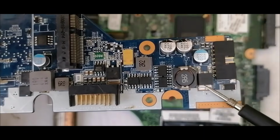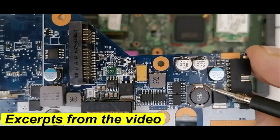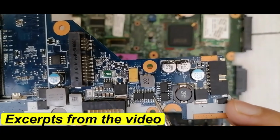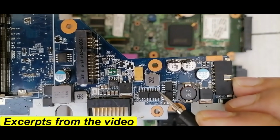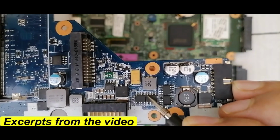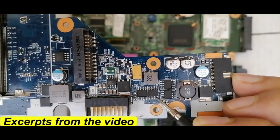So this is a 3 terminal MOSFET. Basically here we have the source, drain and gate, and we have an 8 terminal MOSFET, as you can see. To identify the first pin, we have this white dot here. It means this is pin number 1, pin number 2, pin number 3. So these 3 pins are source. Pin number 4 is gate, and the 4 other pins are drain.